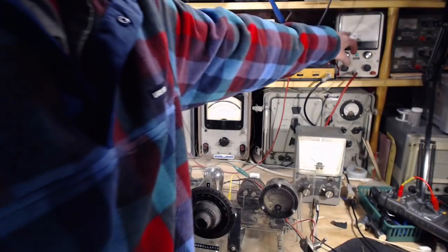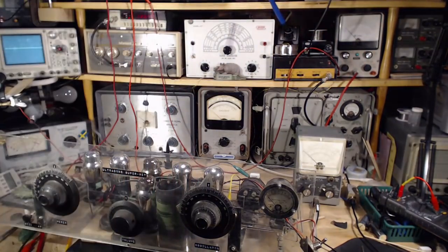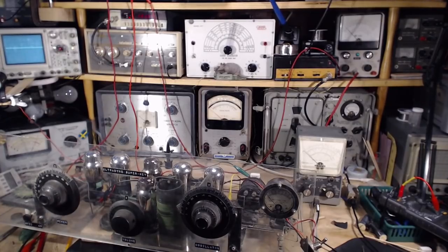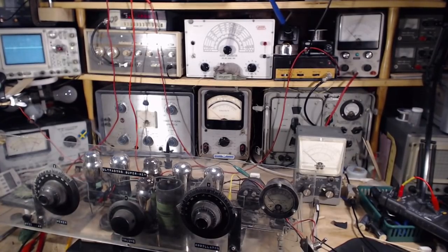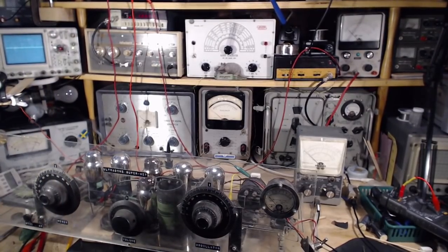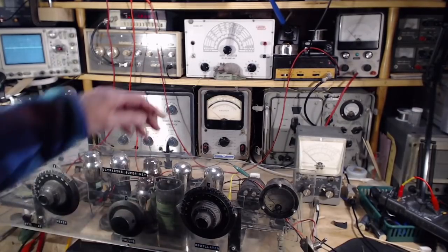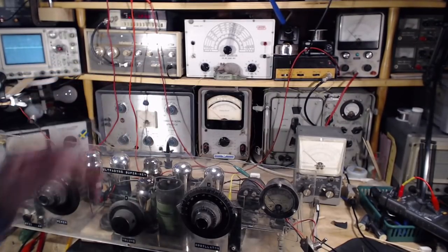This guy up here is going to measure B plus. The B plus, gee, I don't think I really set it. The last time I applied B plus, I just did enough to make one tube work, and then I just stopped. So I don't know where we're going to set that. The radio itself is calling for 45 volts on the particular line that I'm supplying, so that's 45 volts for the plates of these tubes.